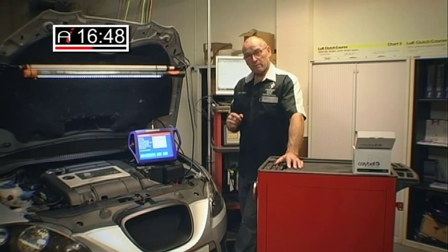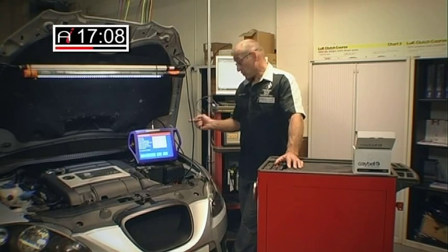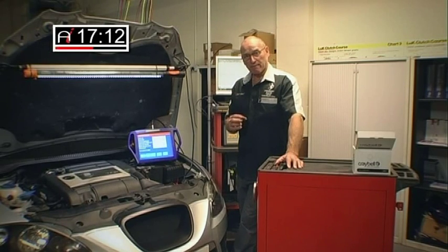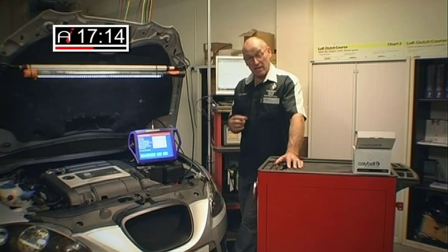We've also used current on analog air mass meters with the same accuracy and results. So it's an interesting avenue we're starting to develop, and we're gaining a lot of confidence in the current that we measure through the air mass meter, rather than looking at voltage and/or a calculated value. It helps us understand that the air mass meter is correctly interpreting the air mass by the change in current flow across the sensing element.